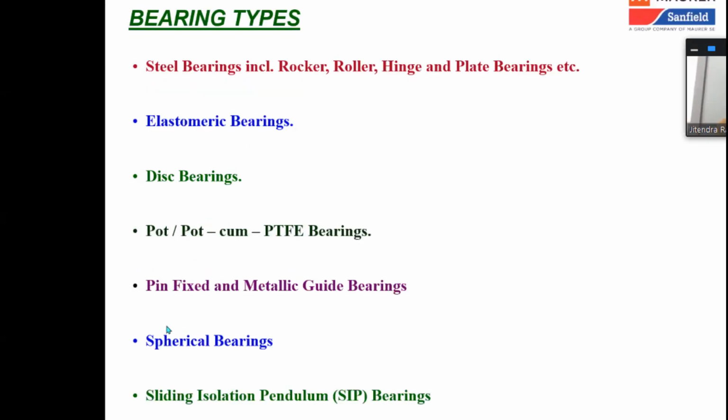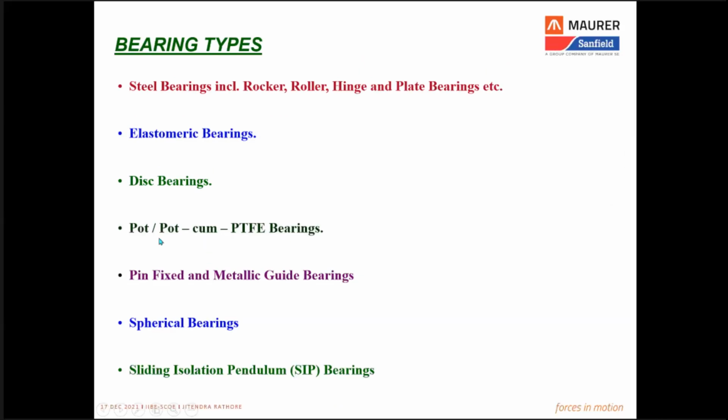Along with pot and PTFE bearings are fixed and metallic guide bearings, which are often used in combination with pot bearings for situations where heavy horizontal force is there. Then we will talk in a little more detail about the spherical bearings, because these are the state of the art and most latest technology and are being widely used in our country these days. And talking about further evolutions, we will also discuss in brief the sliding isolation pendulum bearings.